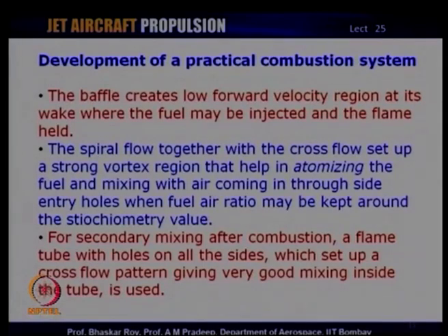That is, the fuel, when it is injected, immediately breaks up in very small droplets, as we saw in the last class, and this creation of these small droplets is extremely vital to the process of evaporation and mixing, and this process, as we mentioned earlier, is called atomization, and this atomizing is an important phenomenon for the process of efficient burning or efficient combustion.